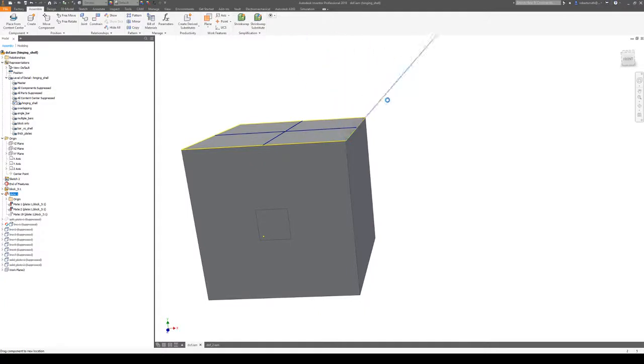So what I get is a situation like this. Okay, there is a load that is not opposed by an equal and opposite reaction force, so it's not a static problem. Essentially, the plate is spinning infinitely, and I do not have a solution. I have an error.